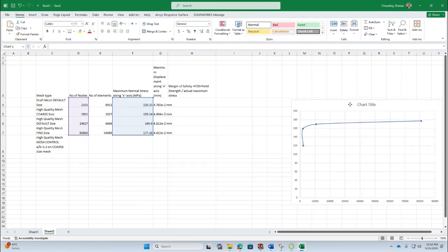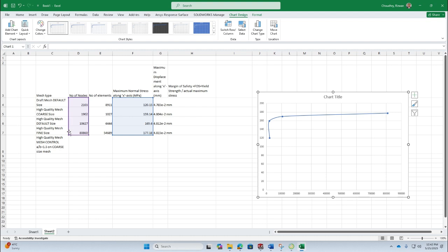Okay. Now imagine that if you had to do this kind of a mesh size for a large part, right? Or a part with complicated assemblies, multiple components together, then if only this small bar had to be meshed by 80,000 nodes or 56,000 elements, what about a large part that will have millions of elements then, right?